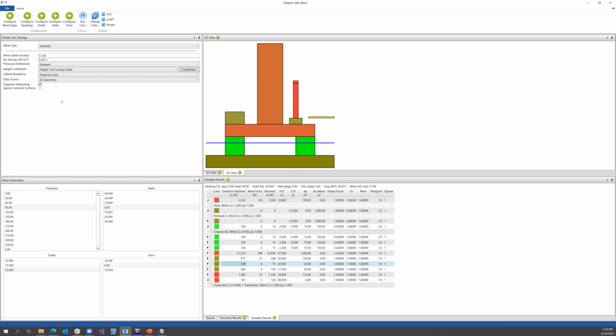So now let's play around with a couple of these settings. First off, we can look at the height coefficient setting, and we can look at the wind exponent and reference height. So we'll start with the default strip size, about 50 meters there. Rerun just that calculation.